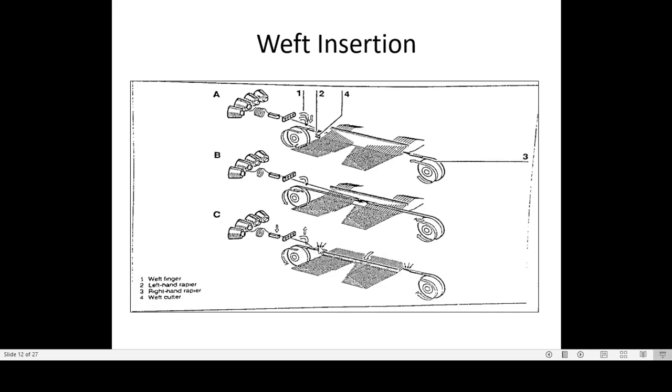When the weft is gripped, the cutter cuts the weft here, and the leading end is ready now. So this is the weft gripping position. Weft transferring again here, transfer to the receiving side. Again the weft tail and hanging length will be there. So the cycle will be repeated. See the figure carefully to see how the cycles are. Three cycles will be there.